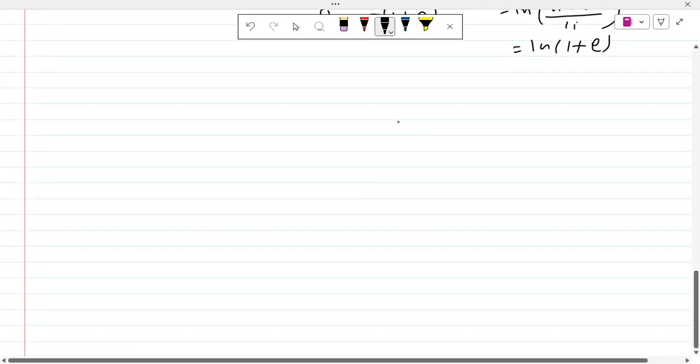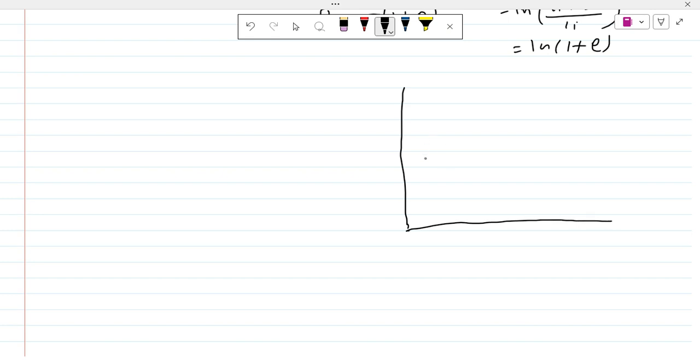Let us talk about the stress strain curve. This is a graph where stress is plotted against strain. Let us talk about the tensile test, as we pull the bar apart. As we apply stress, the strain changes linearly up to some point. This is known as the proportional limit, A. Just above the proportional limit, there is the elastic limit, B.